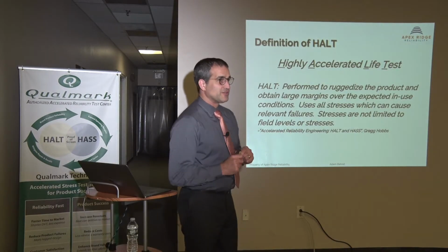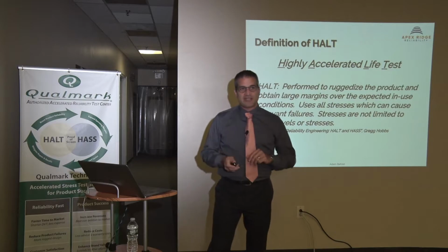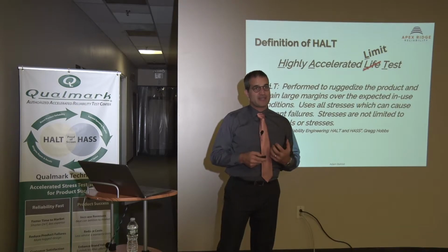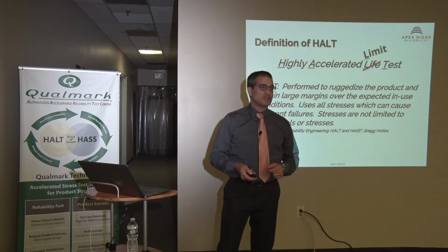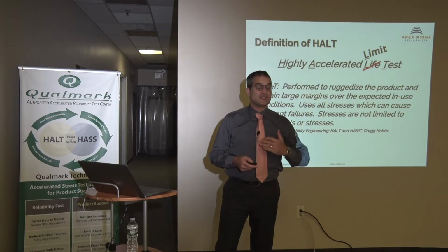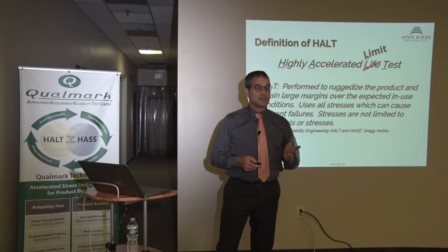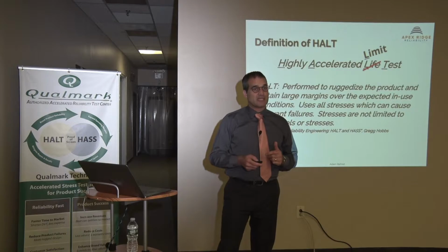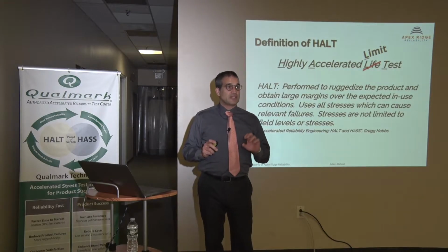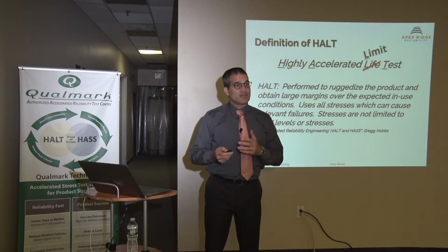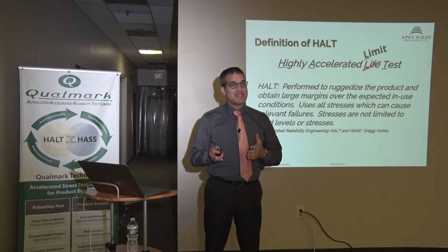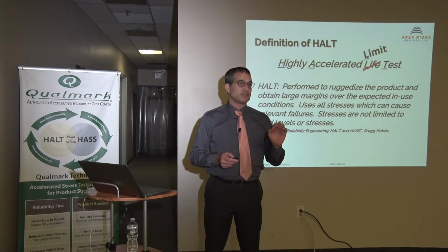So let's talk about HALT for those who aren't familiar with it. It stands for Highly Accelerated Life Test, but it really should be Highly Accelerated Limit Test because it's not commonly used to actually measure life. It's used to understand the limits of the product when stresses are applied to it. And these stresses don't even have to be associated to normal use. And that's what differentiates it from a lot of other types of tests. And we're going to talk about the testing method itself, common ways it's executed, and how it can also be used in the product development process, because that's one of the most important aspects, is that it gains its most value used in specific parts of product development.